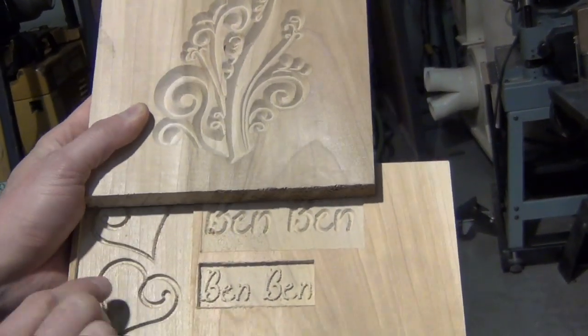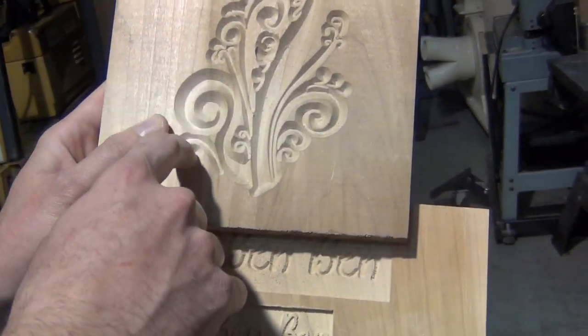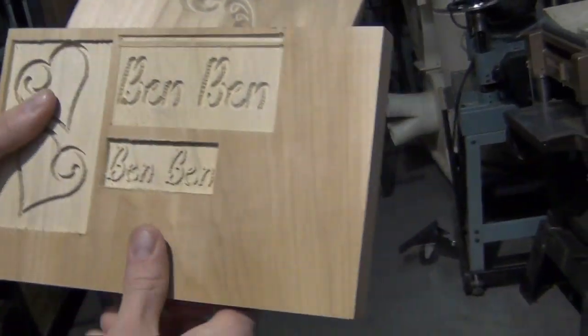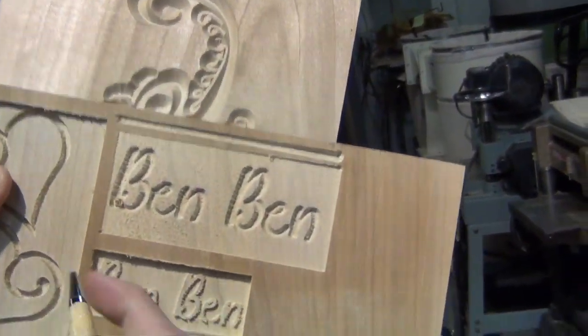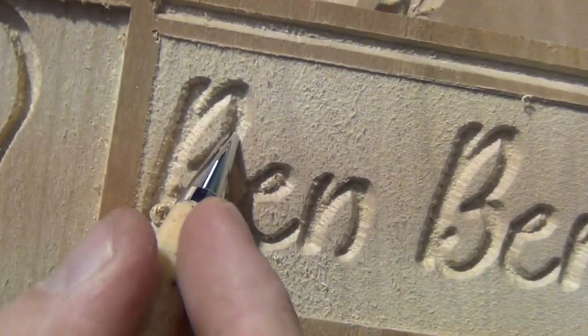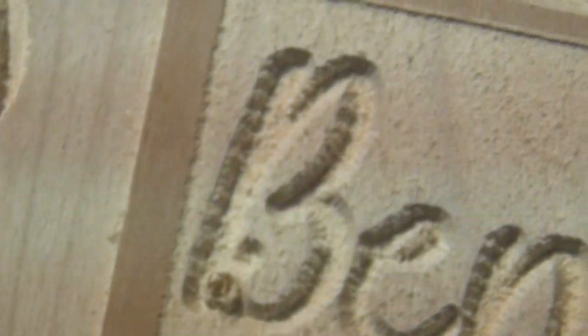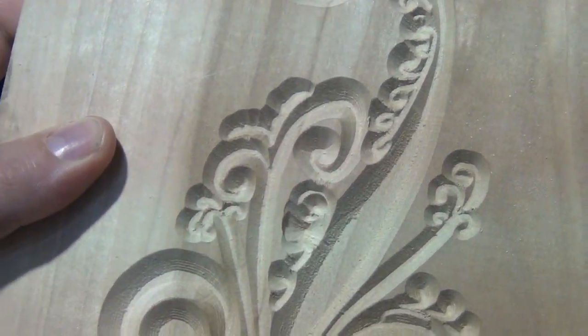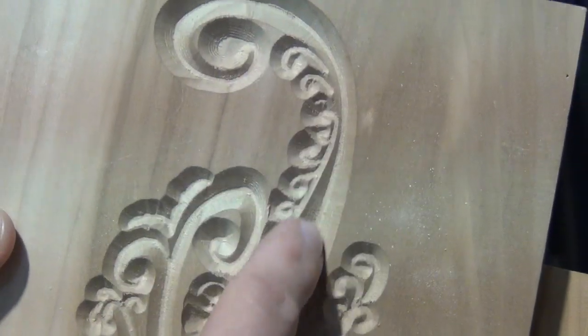The router forgoes all this outline garbage and just does the inside, and it follows the curve. Now the benefit to following the curve, I don't know if you can see this real well, but there's a little bit of tear out inside there. Granted, that's partially the bit as well, but what's happening is as this is going over, it goes down, up, down, up, down, up. Whereas this is continuous, it follows that curve along. And so you have a lot less tear out in these curves. Since it's following that line continuously, it's able to get you a nicer, cleaner cut.